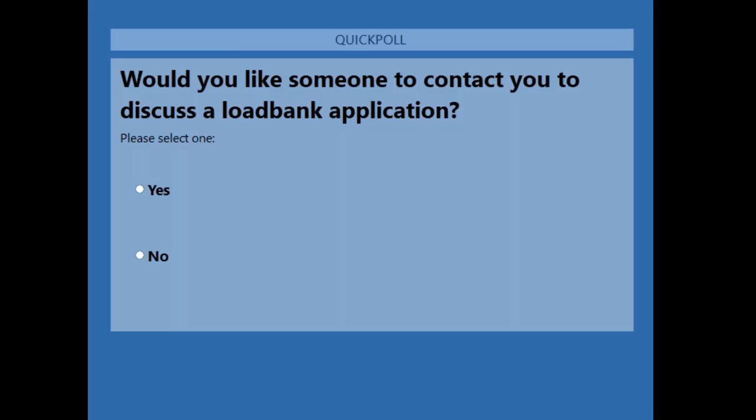Yeah, go ahead, Martin, this is Adam. It depends on if they're using this for load dumping on the load bank versus just doing a standard generator load bank test, in my opinion, because a lot of times we'll see the requirements they want to do up to 110% load bank test. And so then if it was a stationary load bank, it would be sized literally to 110% of the full kW output of the generator.